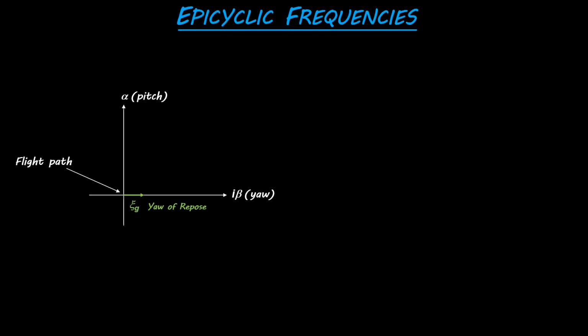All right, so that's that constant little bit of tip in the angle there where it's yawing off to the side. Now, I know that we've used other variables before, but now we're introducing this new variable to represent our yaw of repose, just keeping with the standards in working with this kind of linearized aeroballistics. All right, so first we've got to move off for our yaw of repose to get to the actual nose